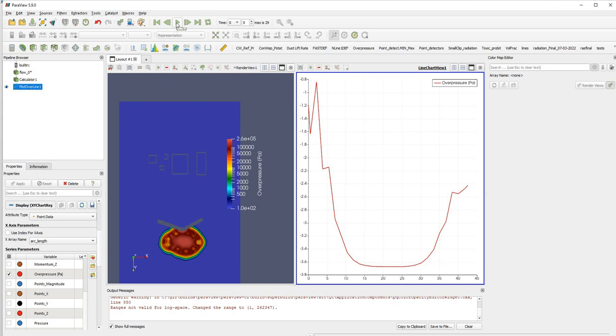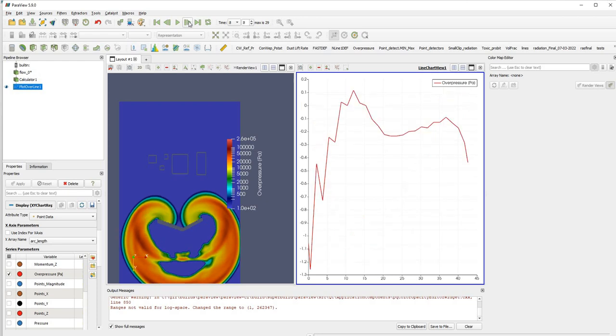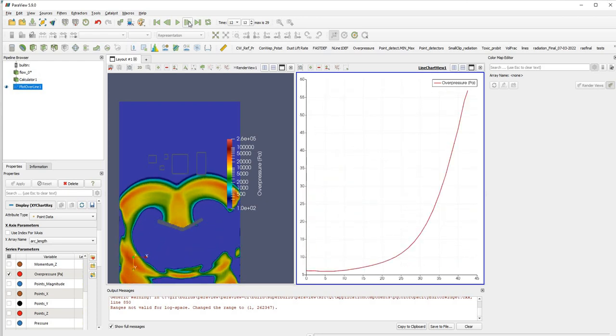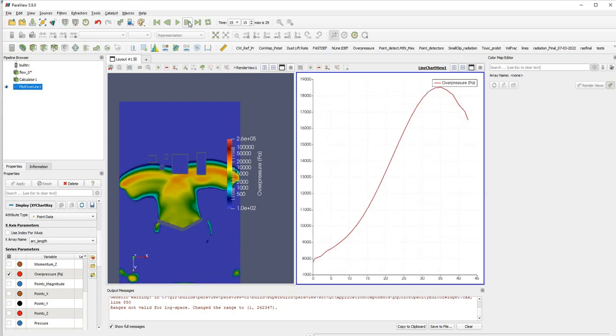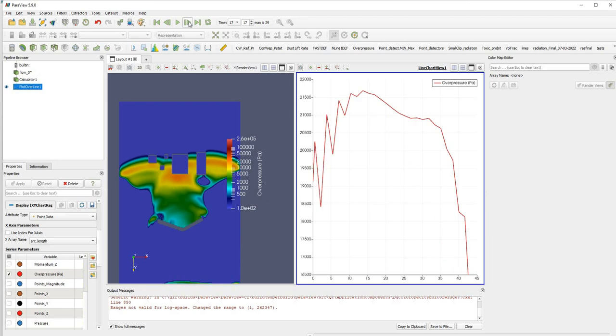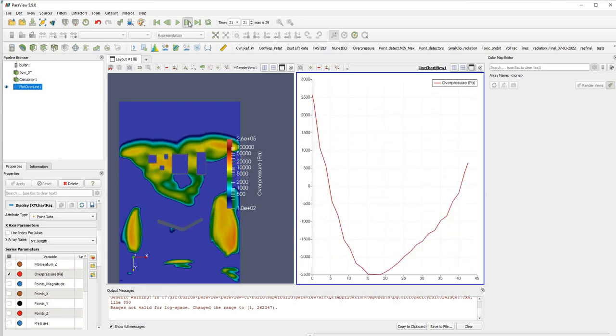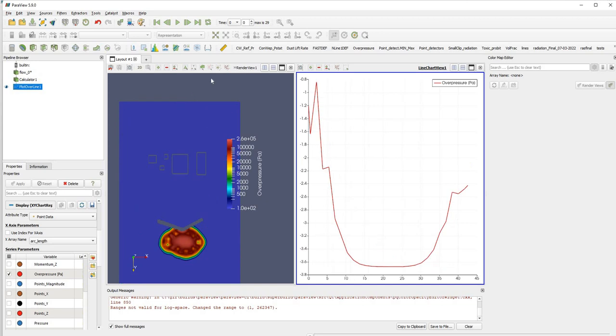But if I scroll through here step by step, you could see it's still noise. But as the shock wave approaches, you could start to see it's still very low, 60 pascals, but now it's starting to climb to 0.19 bar, and this is probably the maximum, about 0.32 bar, and then it starts to drop off again as the shock wave passes the domain. All right, let's go back and take another look.